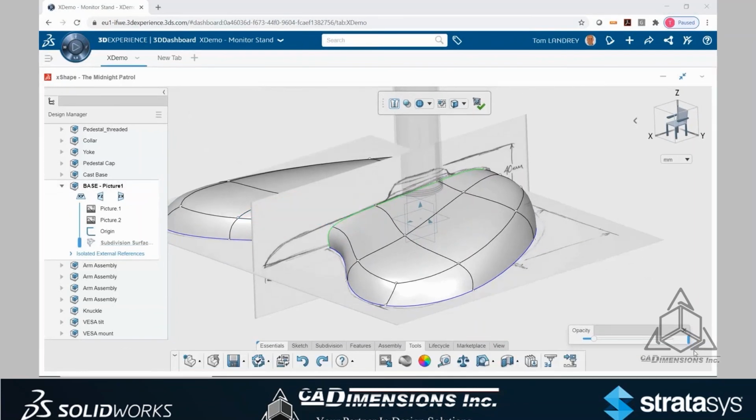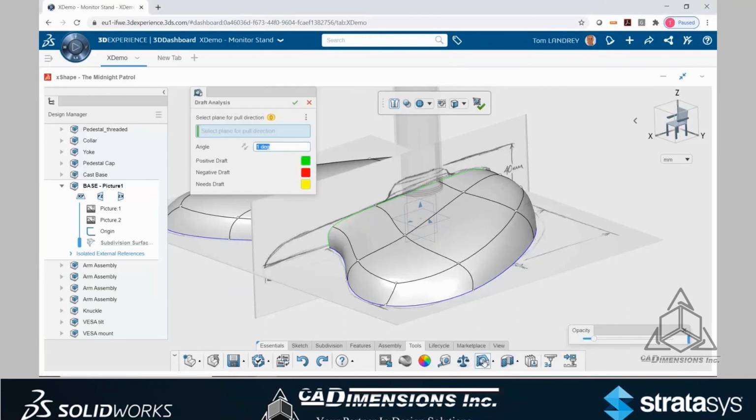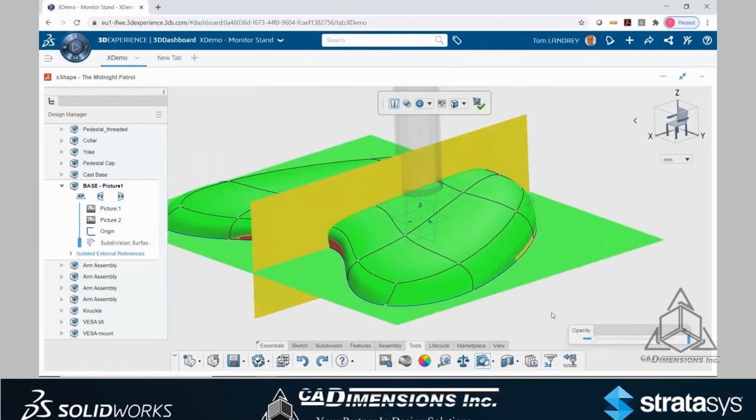So, this is going to be a plastic part, and we have to worry about the part itself. So what I'm going to do is go into draft. We got about 1 degree of pull. I'm going to pull from the top. And notice the red and the yellow. Watch how I just adjust that. I'm just grabbing this particular face and let me slide it. I went the wrong way. Let's go the other way.